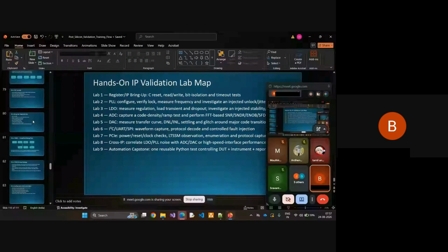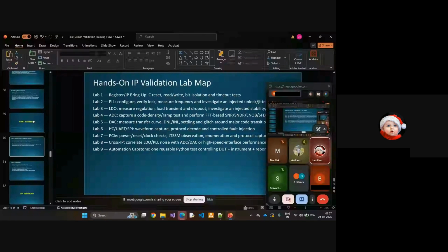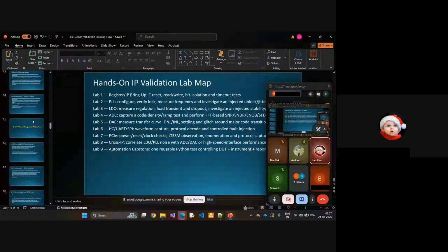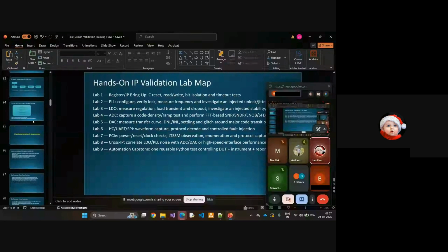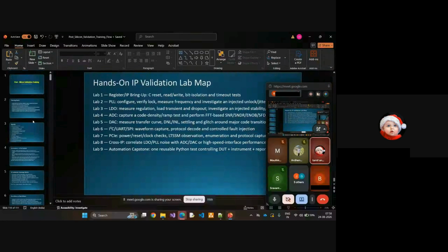See, I've done this PCI validation, but I have not validated through the data. I have just checked the iterations only. We just bring up the link and give an iteration count, let's say 5,000 or 4,000, to see how much time it takes to bring up to Gen 4 or by 4. Yes, but that is not what they're asking. They're asking about the validation of the data they are sending, and how we will validate once you get any bug or a failure in these bring ups.